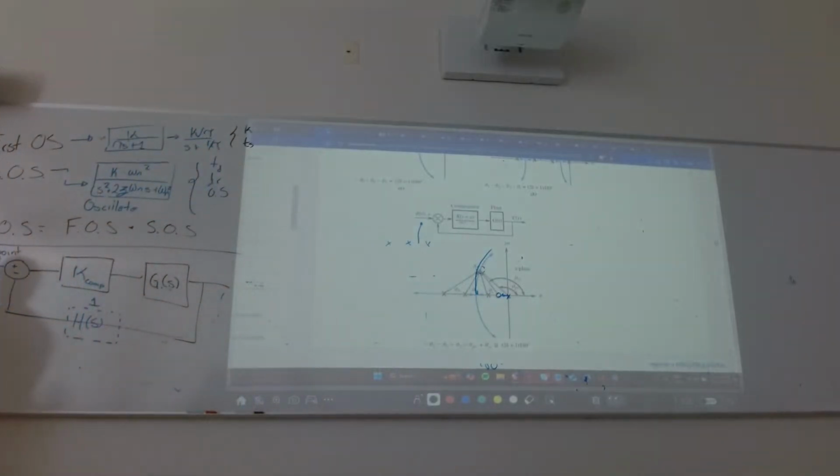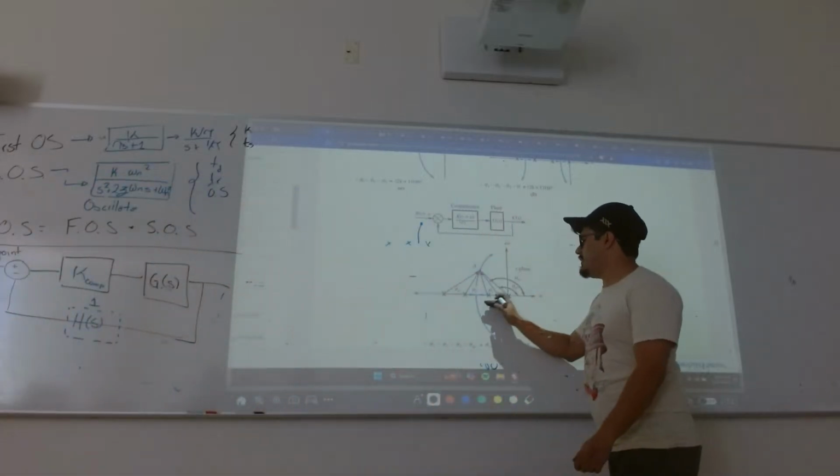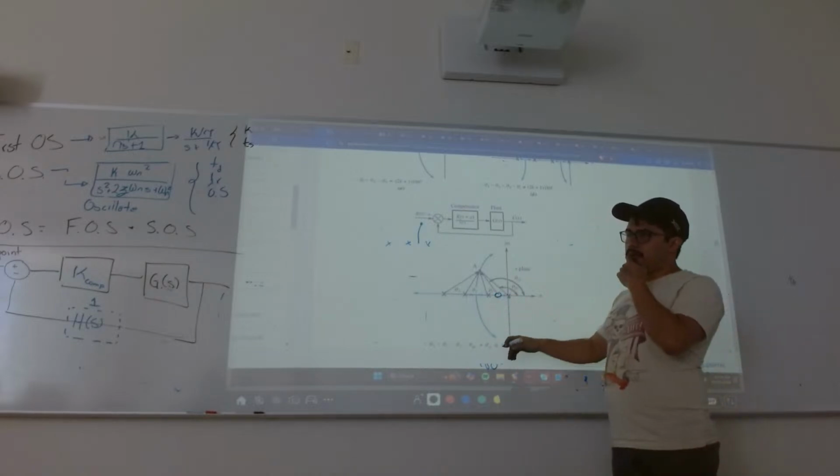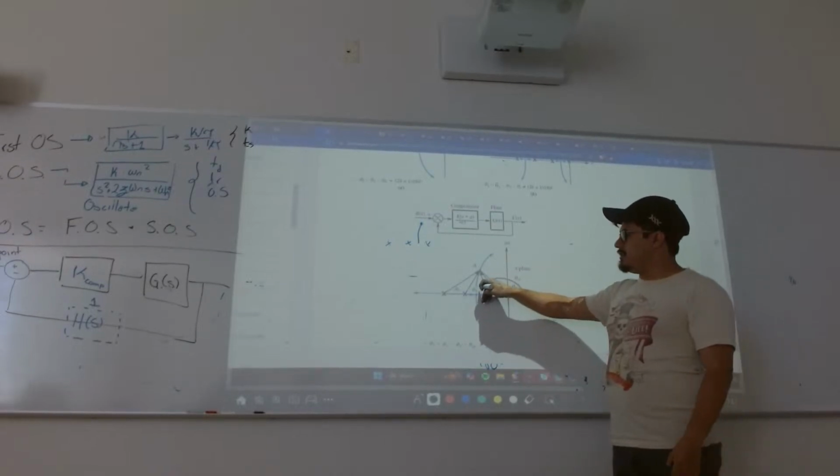Why, whenever we integrate a compensator, for example PD or PI, does the gain reduce? For example, we have a gain of the natural system, then we integrate the PI or PD. In the case it was a PI, its gain was 150, and now it was 550. So why does it reduce? Mathematically, because this guy attracts zeros, and when you attract zeros, you need smaller values of k to move along the line.